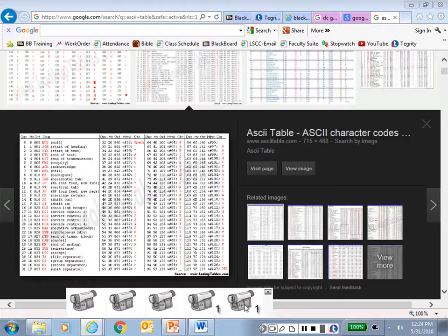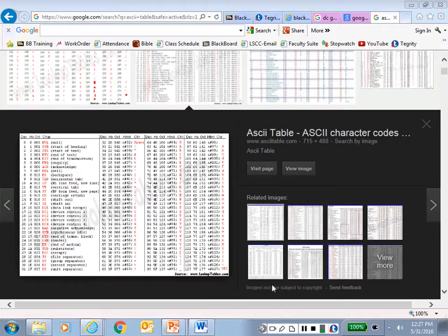When the number 4 galvanizer line dips that tin plate, that metal strip, down through that zinc, it had to go through there at a perfect speed. If it went through too slow, it would put too much on there, right? If you went through too fast, it wouldn't put enough on there, and you would have problems. And you didn't want too much because then it wouldn't get through the rolls, or you couldn't bend it. So most of your production lines move at a precise speed.